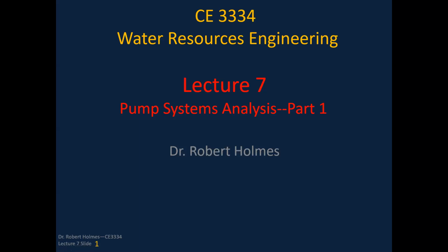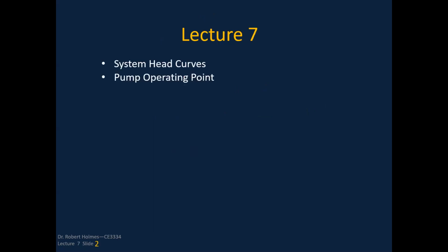Lecture 7 is delving into pump system analysis. We've been talking about pump head curves. Now we're actually going to get down to the point of how do you select a particular pump. So we're going to get into something called the system head curves today, and we're going to talk about how to compute those. And then as we have that system head curve, and we'll couple it with the pump manufacturer's curve or the pump head curve, we'll get the pump operating point.